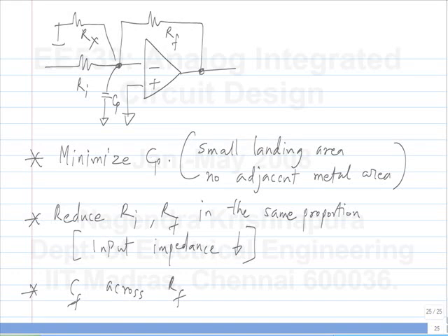Okay, it is largely similar to transimpedance amplifier. One crucial difference is that there the photodiode is giving you some current. You have to amplify that. So the absolute value of RF is fixed. Whereas in this case, the input current you can get can also be multiplied by reducing the value of RI. Of course, this is at the expense of loading the previous stage more heavily. Okay.